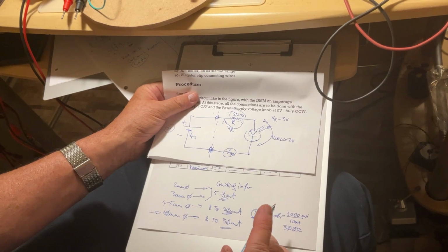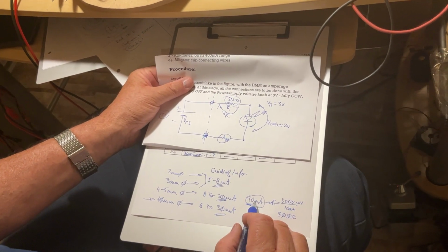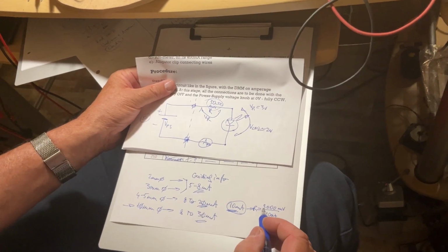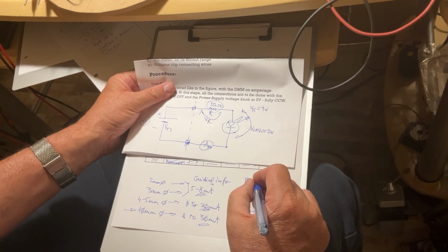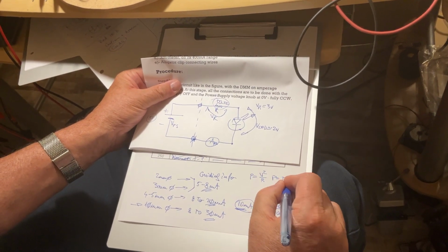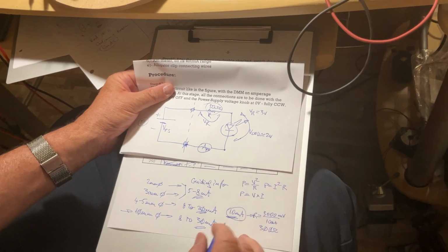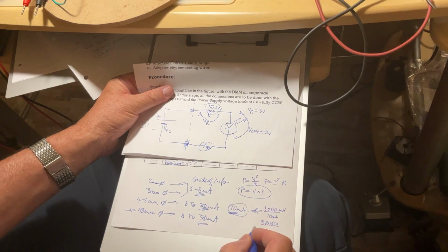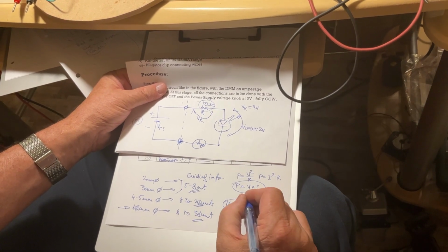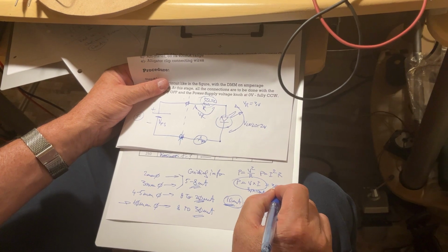What power should that resistor dissipate? Because you don't want the resistor to heat up too much. We have to multiply the amperage times the voltage, because another way to calculate the dissipated power is voltage times amperage. So remember, the power can be calculated as voltage squared over the resistor. It can be calculated as squared current times resistor, or it can be calculated as voltage times amperage. Okay? So this is the one we use right now. And in that situation, the voltage across the resistor is 3 volts. The current is 10 milliamps. So it's going to be 30 milliwatts.